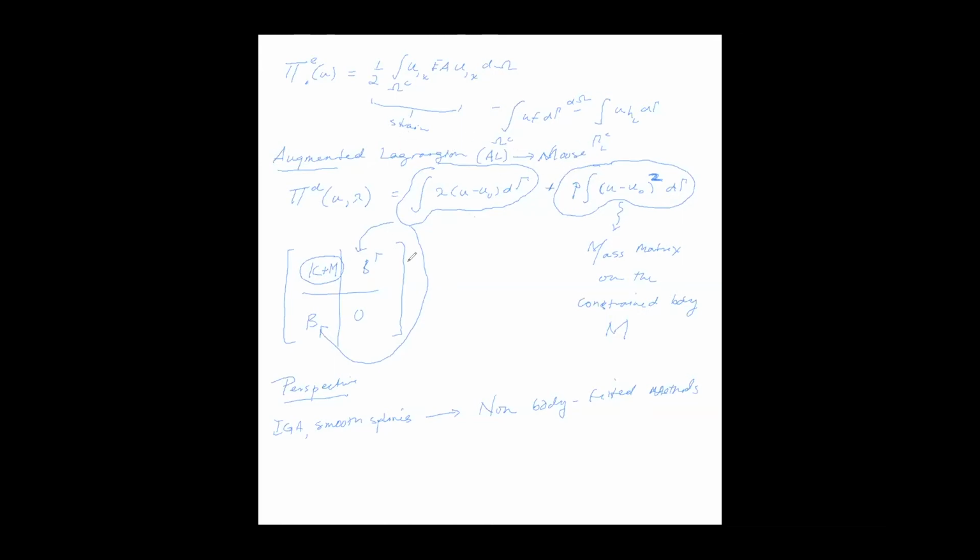a contact constraint, where they basically replace this term with something slightly more complicated that's appropriate for contact. And in order to do implicit contact, which requires the formation of this full stiffness matrix here, they will often use augmented Lagrangian for the exact same reasons, to improve the robustness of their contact algorithms. And it's nothing more than replacing this constraint here with something appropriate for contact. But the structure of the matrix is the same. Nothing changes there.